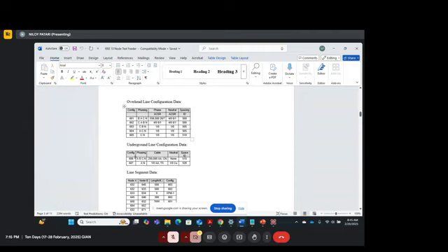There is another thing that you can see here: in overhead lines, 603 and 604 are two-phase lines, right? CBN and ACN, whereas 605 is a single-phase line, right? And in underground, there are two types of underground lines as well. There is 606, which is a three-phase underground line, and 607 is a single-phase underground line.